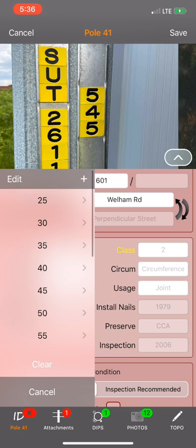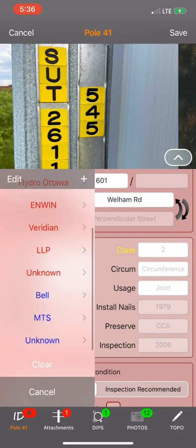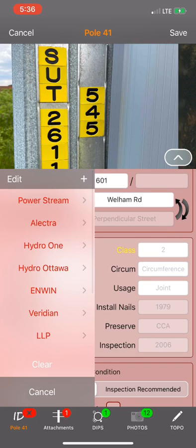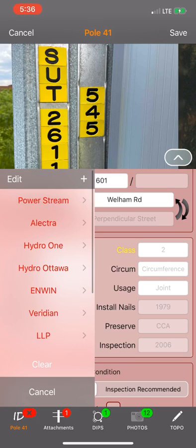That was pretty cool. So you can then select, or you could have just swiped to accept. Now you'll notice that the power utilities are red and the comm utilities are blue. Well, that becomes important because a lot of things will be determined by whether the utility you're adding or choosing as an ownership is a power or a comm. A lot of things downstream will be affected.